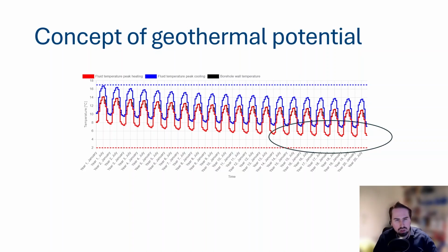We can install some extra heating power on a bore field. We can increase our geothermal heat pump to extract more power from the ground. So yes, there is potential for this bore field for extra power because we do not reach the minimum temperature limits.